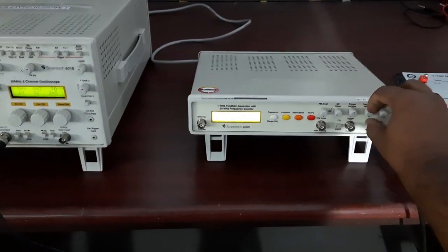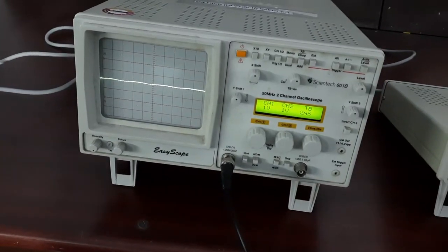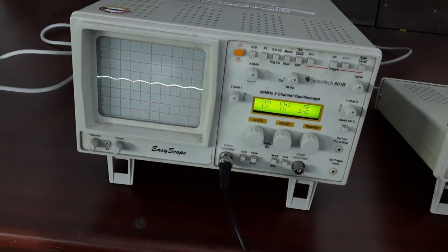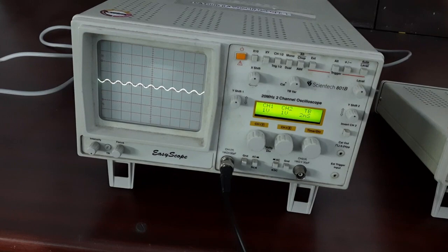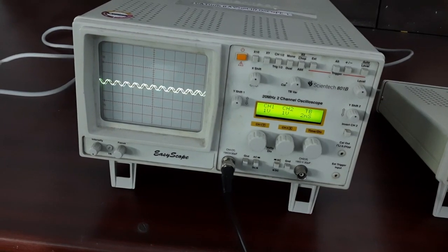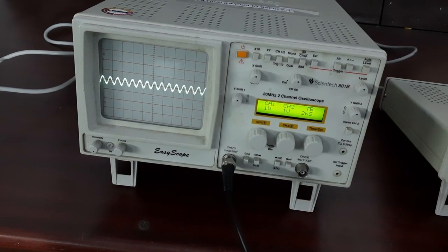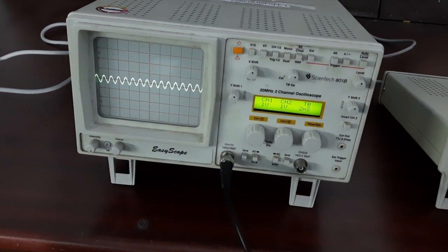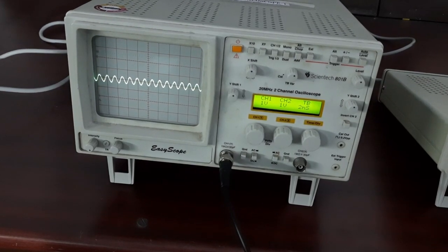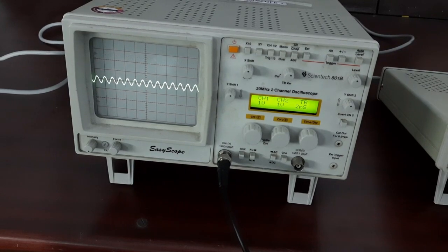Now if I increase the frequency from the frequency variable knob, above 806 Hz, little by little, slowly we will increase the frequency. We can see there is some variable output coming, because we are increasing the frequency, and the high pass filter will allow high frequency. Now you can see a total sinusoidal waveform is coming, because we have increased the frequency enough. It already crossed the cutoff frequency of the high pass filter.